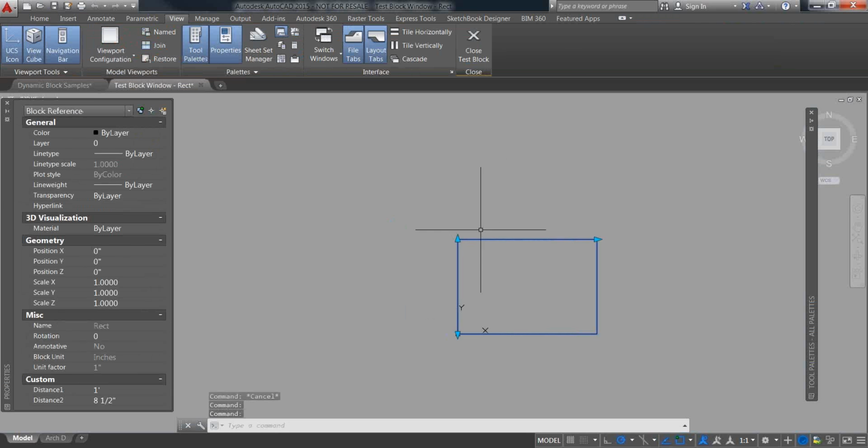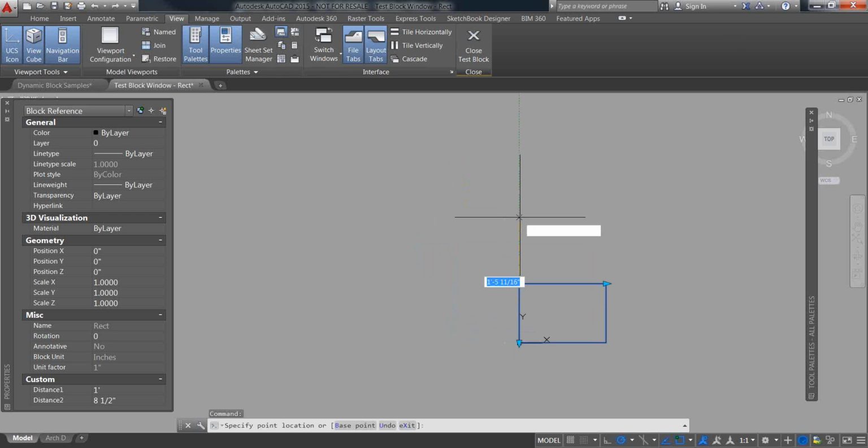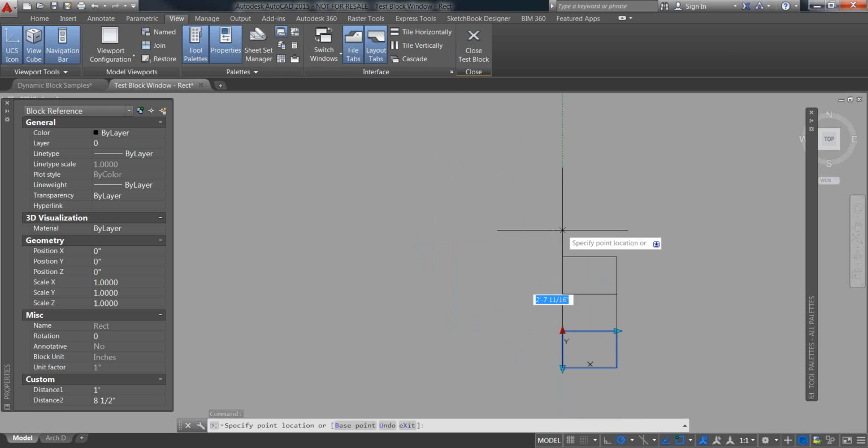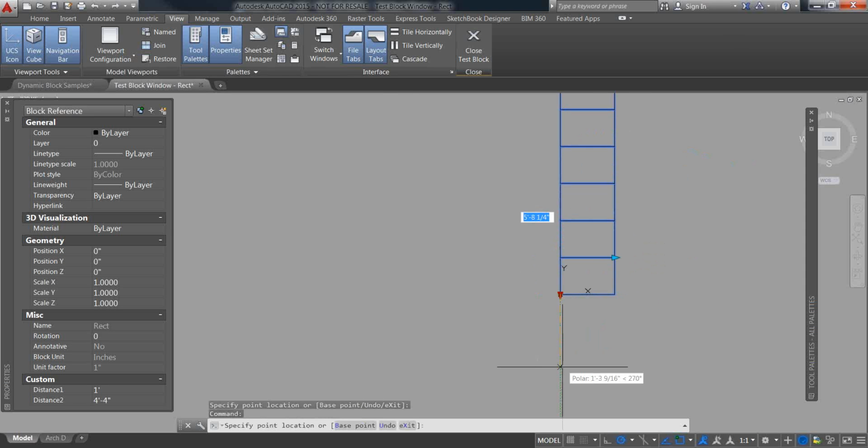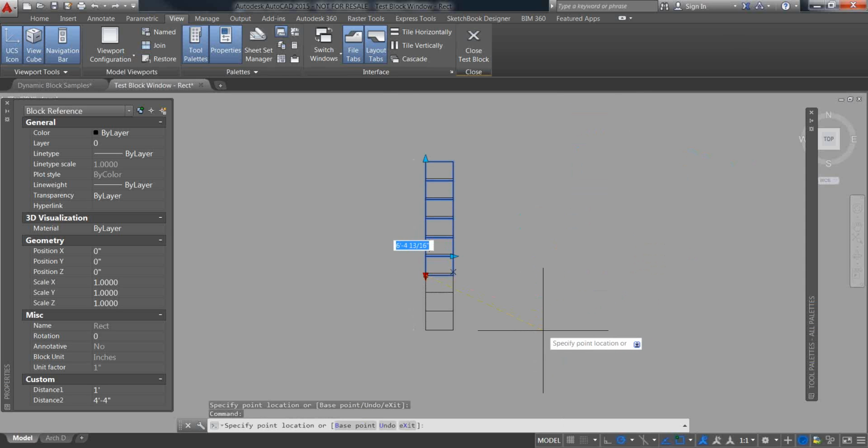And we'll see now when I select this block, I get 2 more of these triangle-shaped arrows. When I drag that arrow out, AutoCAD is going to make an array of that block at whatever distance or point that I select. And because I didn't change the default, I can actually array it. Looks like I got a couple of blocks stacked on top. I think I might have confused AutoCAD there. I was trying to pick the array grip to run that in the opposite direction.